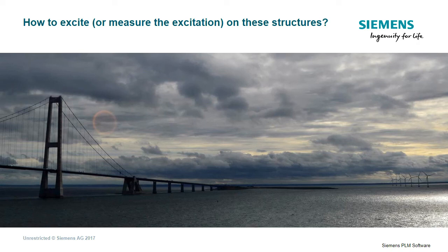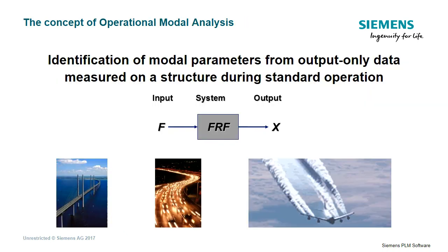Being able to identify a modal model on those types of structures in operating conditions would, on the other hand, be extremely useful, in particular to have an estimate of their actual damping values, and consequently improve the accuracy of, for example, fatigue life calculations or flight stability calculations. To cover those cases, operational modal analysis was introduced in the 90s.